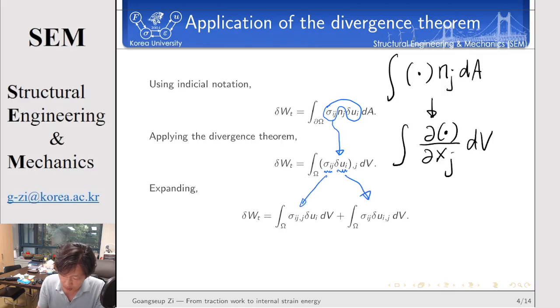So here, look at the first term, the equilibrium condition. If we don't have body force, meaning body force is equal to 0 in the continuum version, and my continuum is in equilibrium, the derivative of the stress tensor with respect to coordinate should be equal to 0. But what if body force is not equal to 0, like gravity or magnetic force? Then we need to have extra terms.